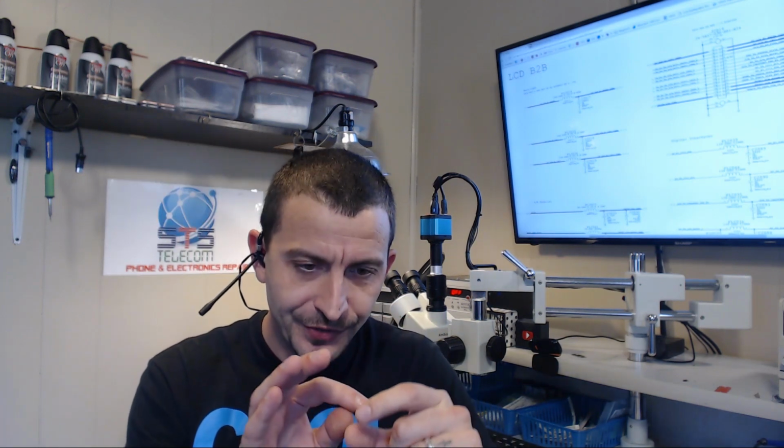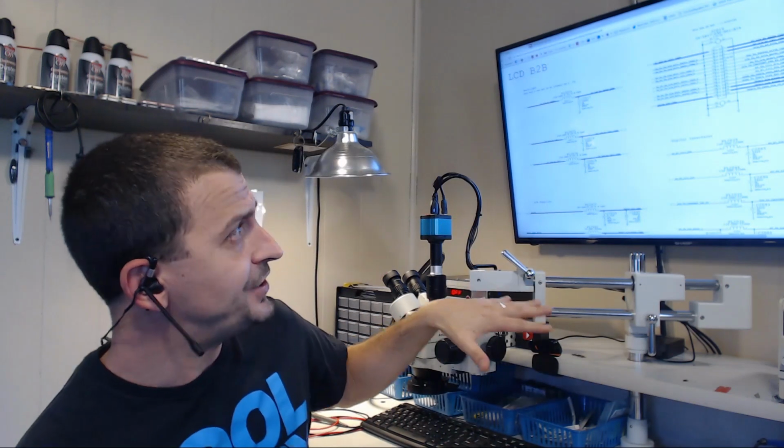I was able to put in everything, but I didn't know exactly what size to get. So what I wound up doing was taking the original coil and putting it under the microscope with a ruler and measuring it. I put in all the parameters I needed to match this up on DigiKey. To get the exact right coil, I was about a half millimeter or a millimeter too tall. And a millimeter is like the height of the CPU, and you can't just double the height of the CPU and think life's going to be happy.